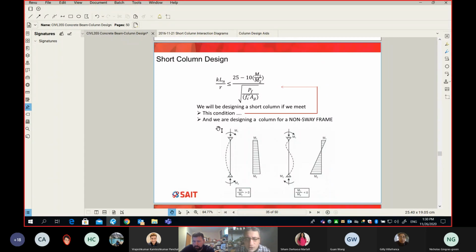There is no third option. Unlike steel, where every steel column must take buckling into effect. In concrete, it is not like that. You either take the buckling into consideration or ignore it.